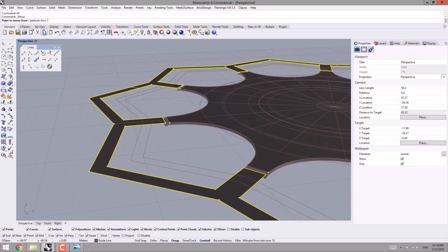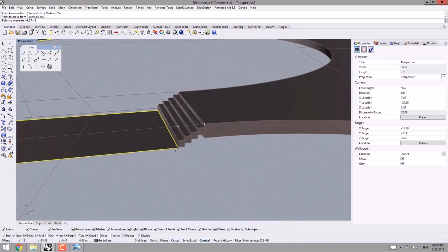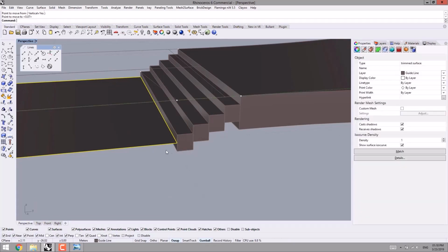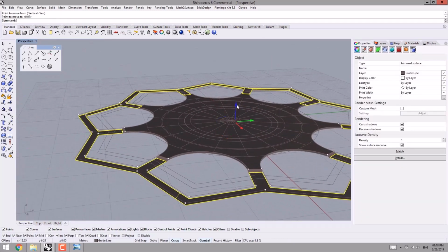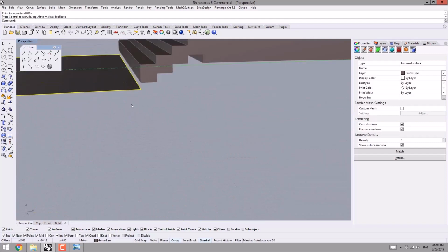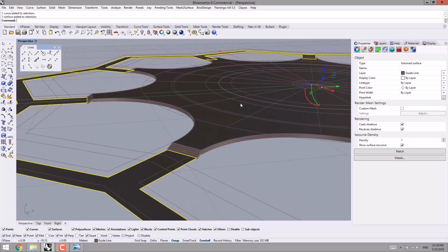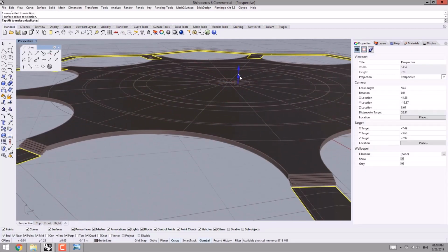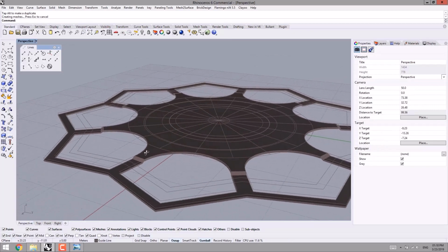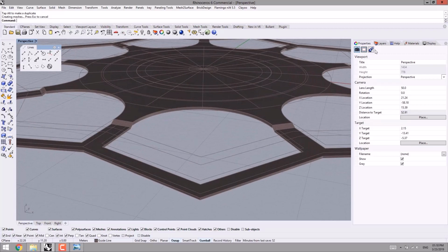Let us check it out in the perspective view, and then move command. I set it to vertical, and then I move it along the z-axis under the stairs by this way, and let me move it downwards. Well done. Then again I want to select the surface and then extrude it a little bit by this order, as you can see.